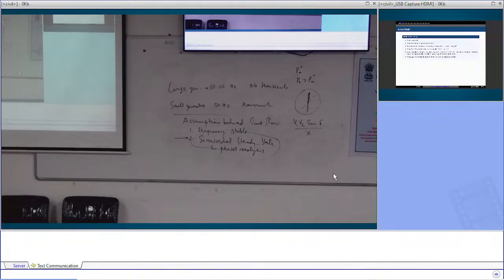But when the changes are large, we use other type of theory, not that one. So this is the story of what power system is happening. And ये हमको हमेशा we have to have always on the top of our head. So when you said frequency change, it is the change in the speed of those big generators which we constantly monitor, and that tells us there is a difference between generation and demand, and we change the generation, that is the mechanical power going to the generator, as a function of that change in speed, because that's the only sensor we have.